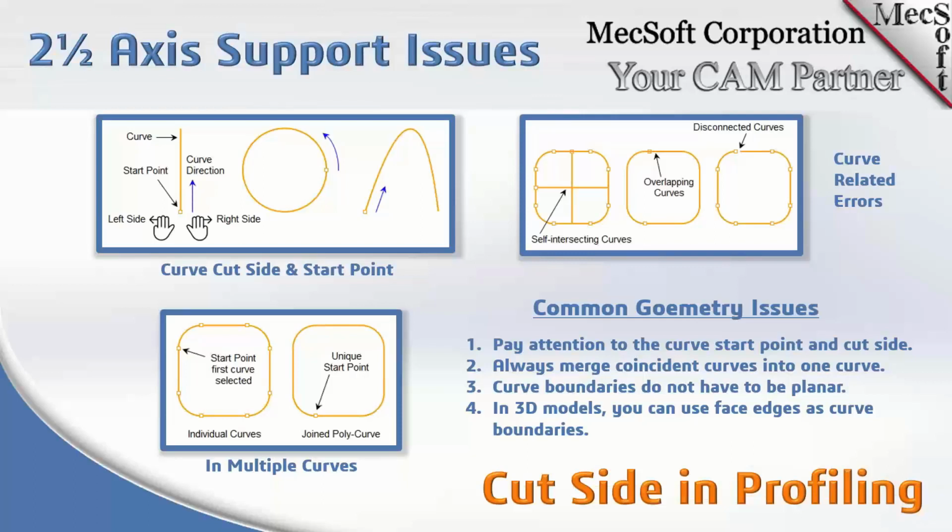Follow that procedure by merging your curves. Double check that it is a single curve. You know where the start point is. That way, when you machine it, you understand which is the cut side, where the start point is, etc. Also, on the far right, problems can occur if your curves don't connect. If you're doing a continuous cut and you have multiple curves, you more than likely want those curves to touch end to end. If they're not touching end to end, you're going to end up with separate start points. You're going to have a gap in your cut.